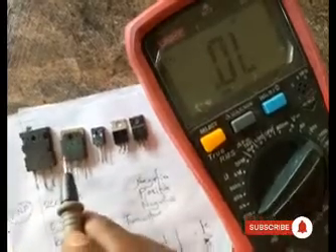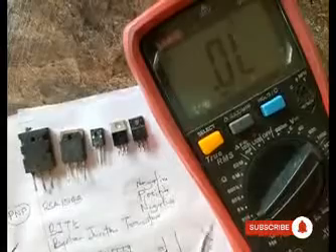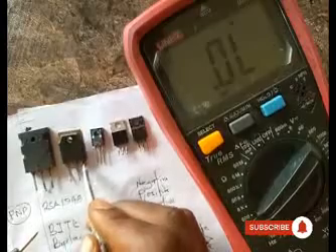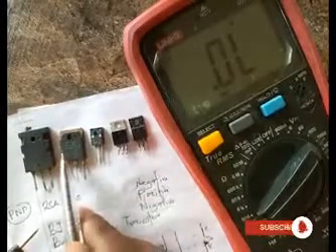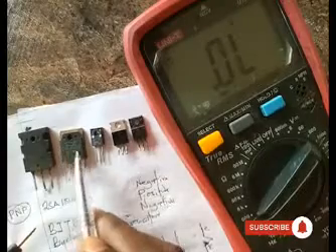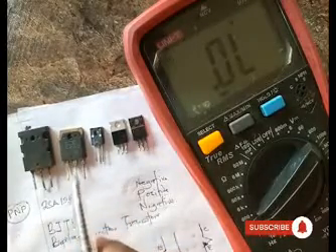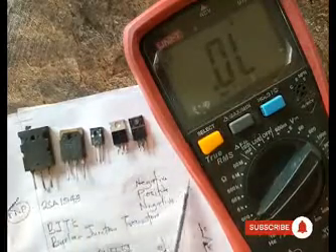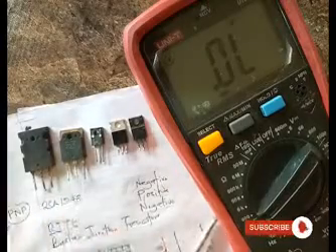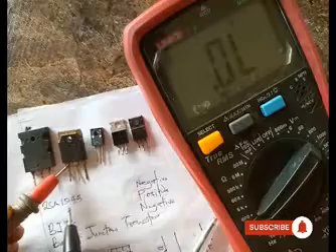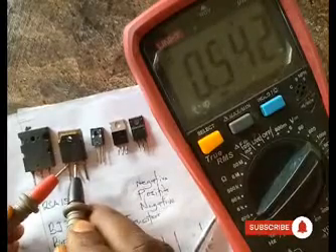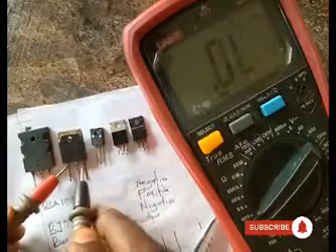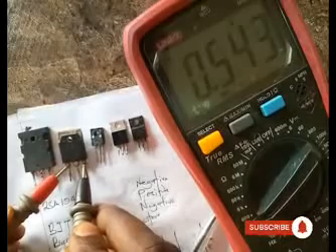All right, now let's test the next one. This is C4468. Already, like I said, I've checked the data sheet and I know the pinout. This is base, this is collector, and this is the emitter. All right, and obviously, like I mentioned earlier, it starts with C, so this is an NPN transistor. Now, this mustn't be the case every time, okay, but for most of them, it's a key you get to use. All right, now if this is an NPN transistor, it means that a positive probe will be on the base. Okay, now let's see, 0.542 and 0.543. So once again, we see that this is the emitter because we have a higher reading there.